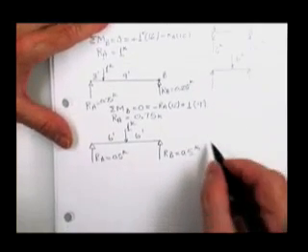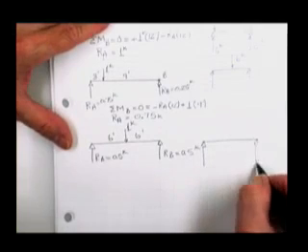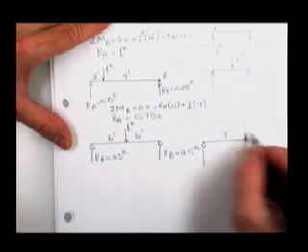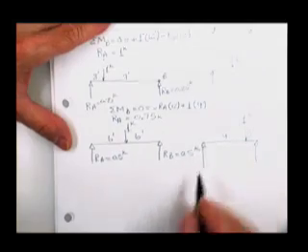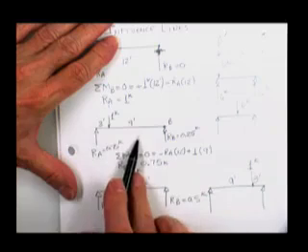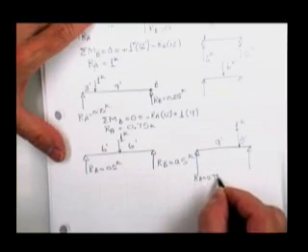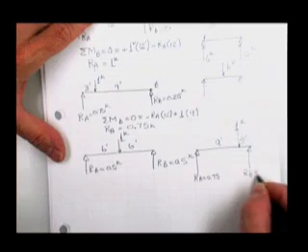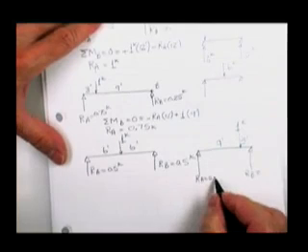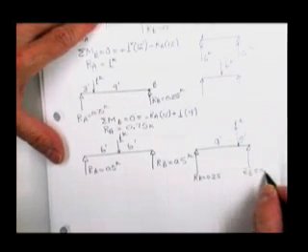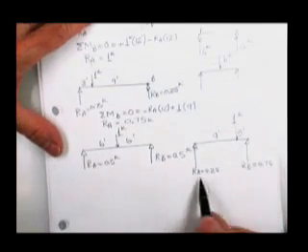And then if I finally put the load at the 3/4 mark, then this reaction here looks just like this, reversed: 0.75, and the reaction at B is 0.25, got to reverse them, and 0.75. And when the load goes right over the reaction at B, the reaction at B will be 1, and this guy will be 0.